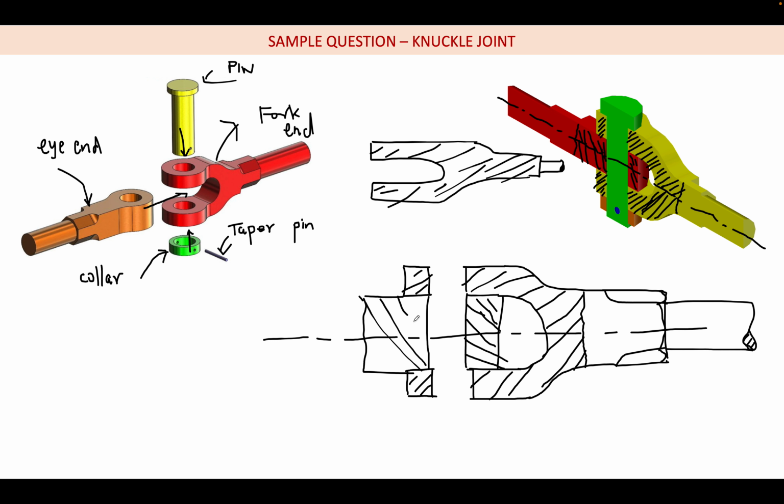If I show plus 45 for one, then for the other material, the eye end, it is minus 45. Here I am going to show the octagonal profile, something like this after filleting those things. So this portion can be represented. This is only for the representation purpose, and then we have the shaft. Like I said earlier, the shaft and the octagon we are not sectioning.